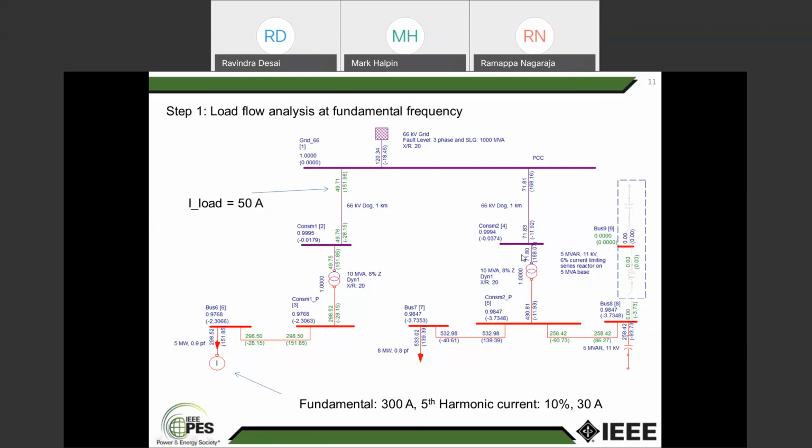Now, this is the consumer who has got actually the 10 MVA 8% impedance, and this load power factor is very poor, 8 megawatt, 0.8 power factor. Therefore, in order to mitigate the load power factor, in order to see that actually he's going to maintain a very good power factor, he's going to have 5 MVA capacitor bank here. Now let us see what are the various cases, what will happen if he has got mere 5 MVA capacitor bank without the current limiting reactor here, what happens, that also we'll try to understand.